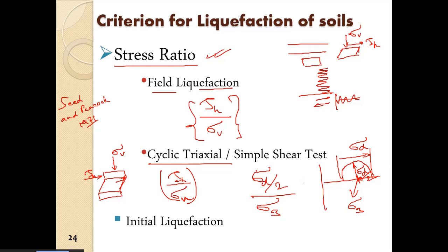We have to understand the various stress states in the soil, the relative density, the void ratio and the stress state, and the interaction of all of these criteria together, to understand whether there will be liquefaction initiated in the soil or not.